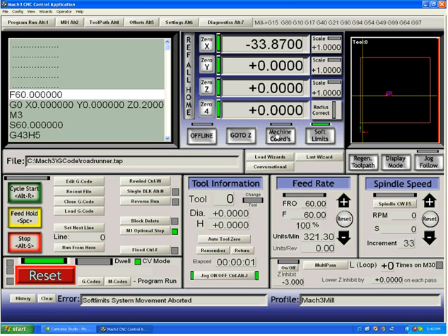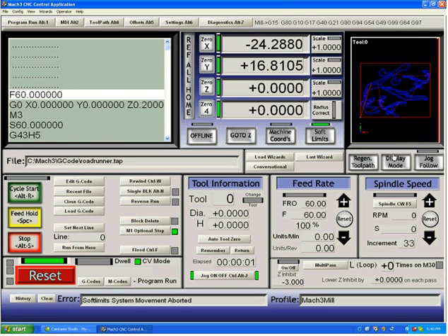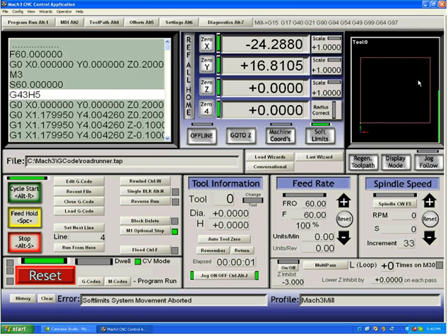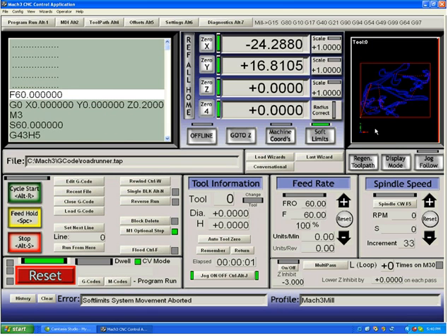But the system will not let me jog past 0. It just simply stops me. That stopping is automatic and works on all home limit, all axes that have a soft limit enabled. And as long as your soft limits are hooked up properly, you'll know it by being able to select your display mode button. Otherwise, your display mode button will show you a nonsense image, which really doesn't mean much.